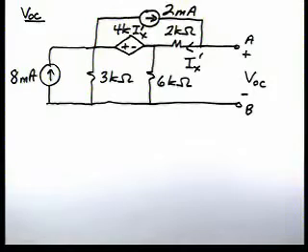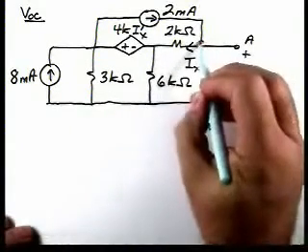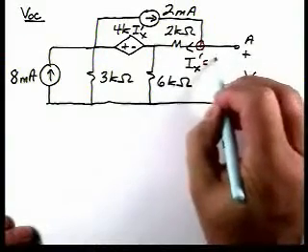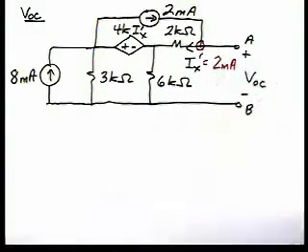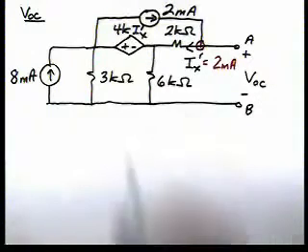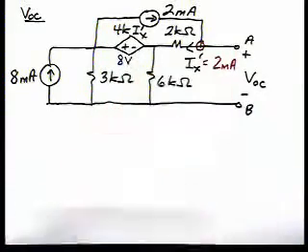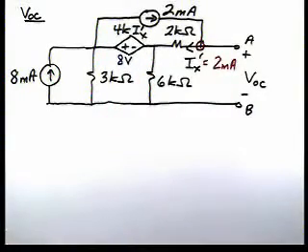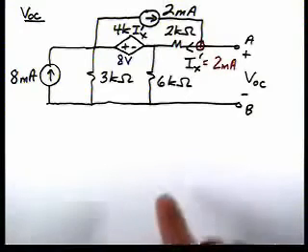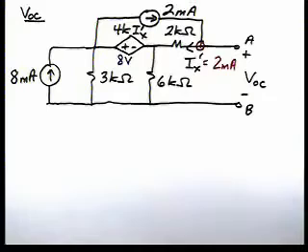And if we look and say, what technique should I use? Let's look at the circuit. For instance, if we apply Kirchhoff's current law here, we see that Ix prime is 2 milliamps. That means this voltage source has a value of 8 volts. So that voltage is known. So if we were to look, we could do mesh or nodal, either one. And what I'm going to do is, let's do this one with nodal.